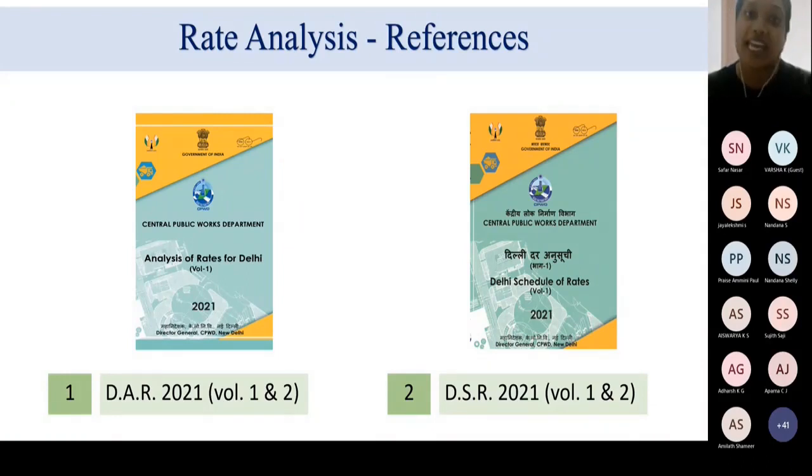You can employ 10 people to mix and place the concrete, or you can use 5 people and a machine in order to cast the slab. This is an alternative. You can reduce the number of men and increase the number of machineries, or you can use only men. The choice of the method of casting the slab will decide the rate of executing that particular work.